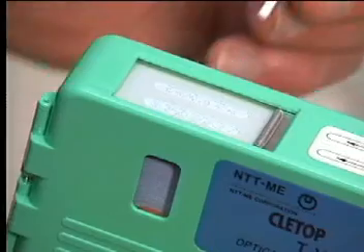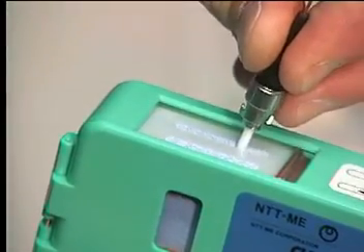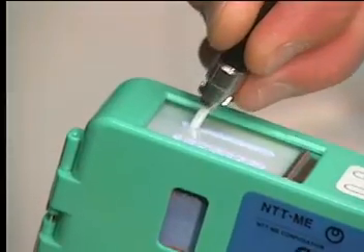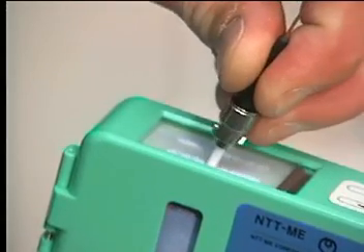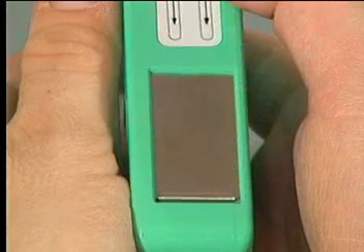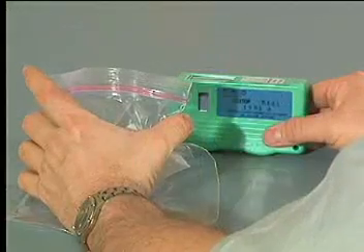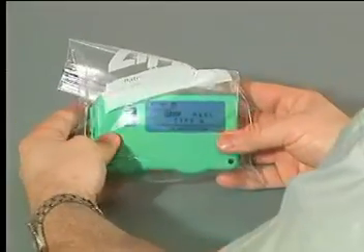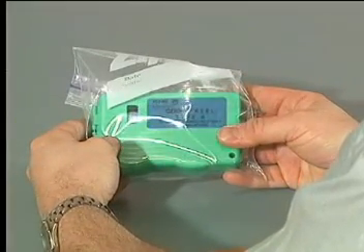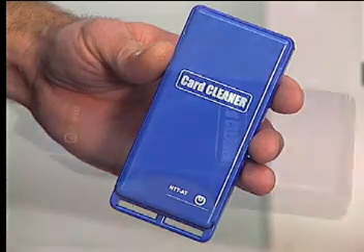Although highly effective, the mechanics of cleaning cassettes can be awkward to use at times. And because they require the connector to be wiped across a surface, there is a slight possibility of scratching should an abrasive particle find its way onto the cleaning tape. The protective flap may not exclude these particles, especially if the cleaner is kept in a dirty environment, like the average toolkit or a dusty pocket. To reduce the possibility of damage, keep the cleaning cassette in a Ziploc bag and change bags periodically.